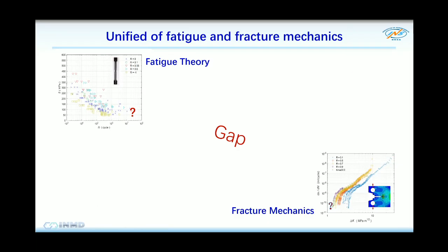And we also have a crack growth zone based on fracture mechanics. We also have changes about the crack growth ratio. This does not exceed, or we bring on this critical point. So between the fatigue and fracture mechanics, there is a big gap. This gap is durability. So we have the fatigue zone, we have the fracture mechanics zone, and we have the durability zone.